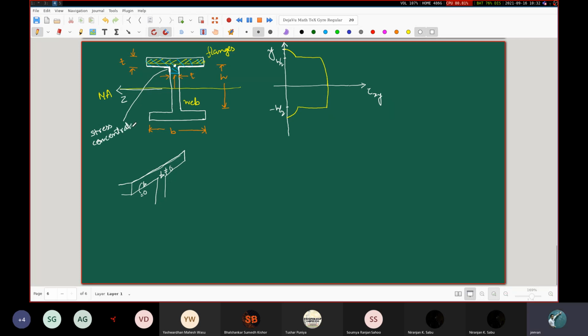They can give rise to very high values of the stresses, which is why in real practice, when these beams are actually fabricated for practical use, they try to make these things slightly smooth. They artificially make these things slightly smooth, like this. Furthermore, you have sharp corners here, so they try to smoothen this out also. Here also they try to smooth it out. So that in as many places as possible, they try to smooth these sharp corners.